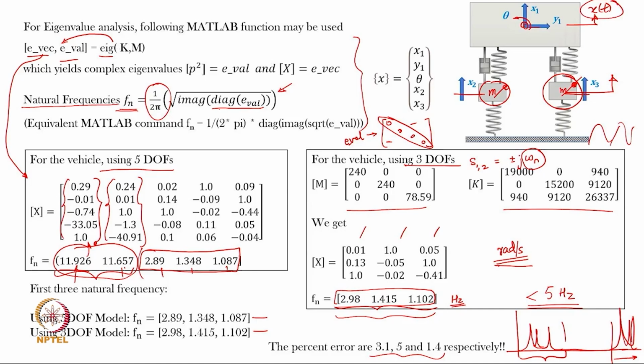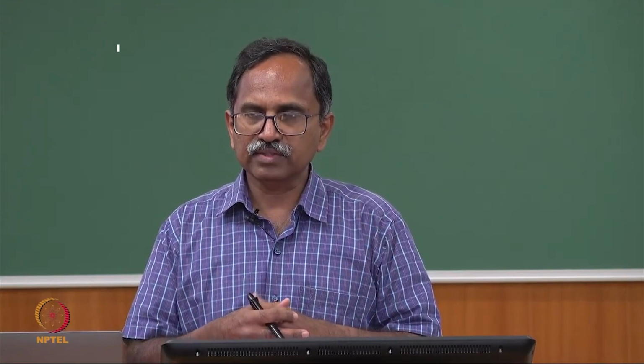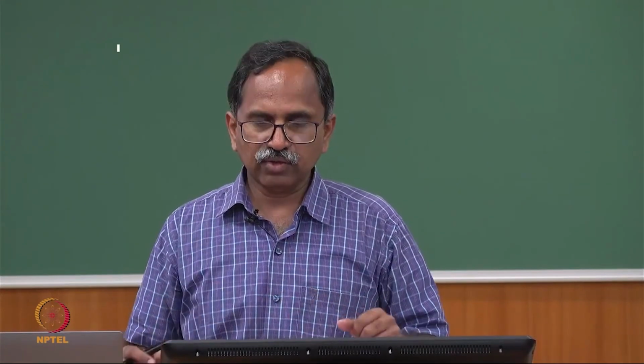So, all of these considerations also decide the degrees of freedom that you need to account for. Therefore, it is always said that your first step of capturing the physical system as a simplified vibratory model is governed by your own experience of what the system is all about, your final goal or target of your analysis process, what exactly you want at the end of the analysis. That will decide how complicated or how simplified the model you make out of the physical system.